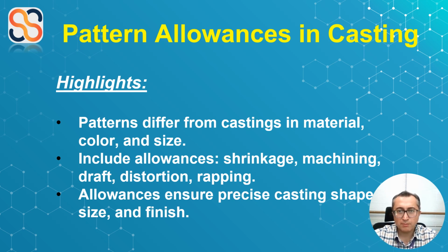Patterns are often made in multiple pieces, while the casting itself will be one solid part after cooling. Sharp changes or intricate details are avoided in the pattern, since they are easier to add later through machining.